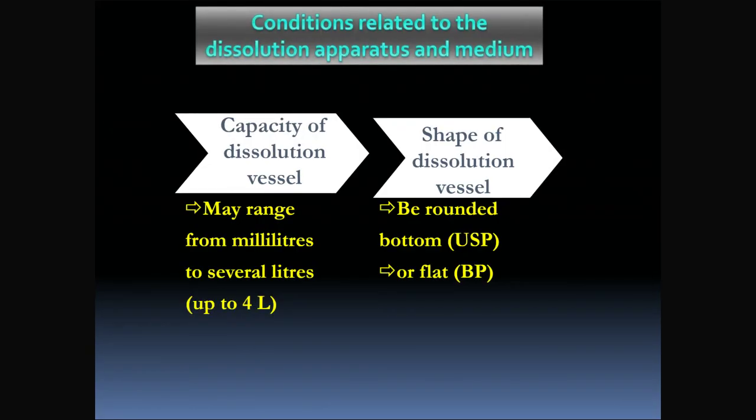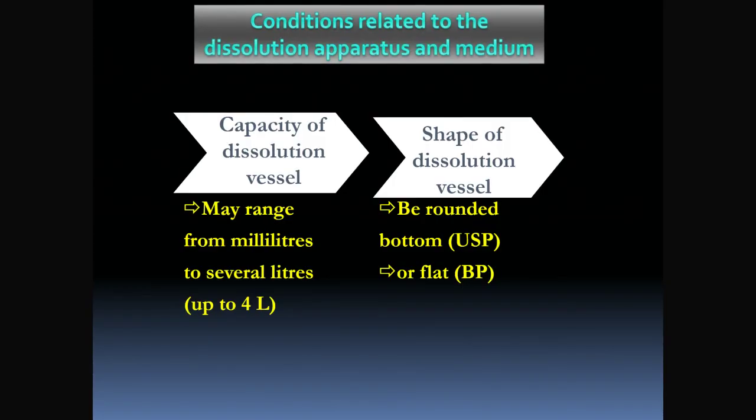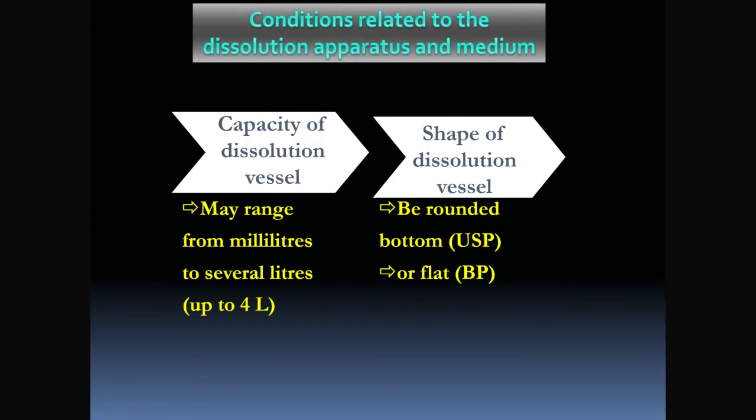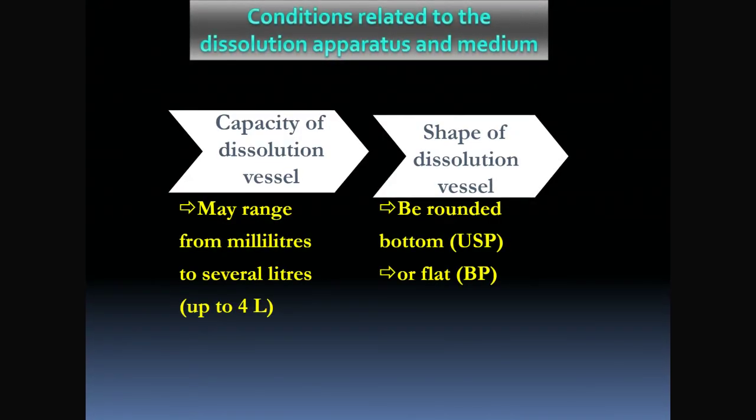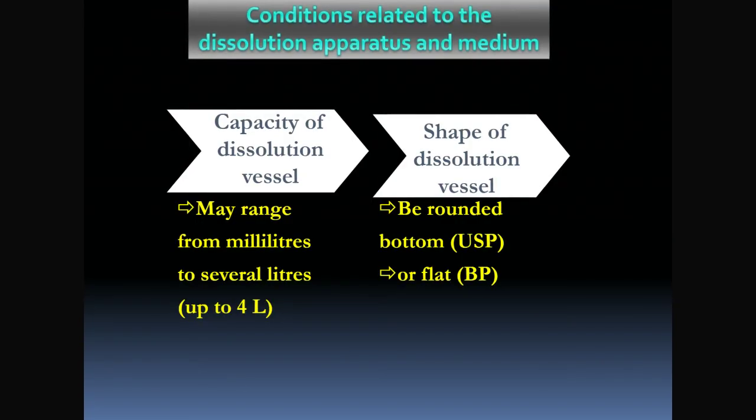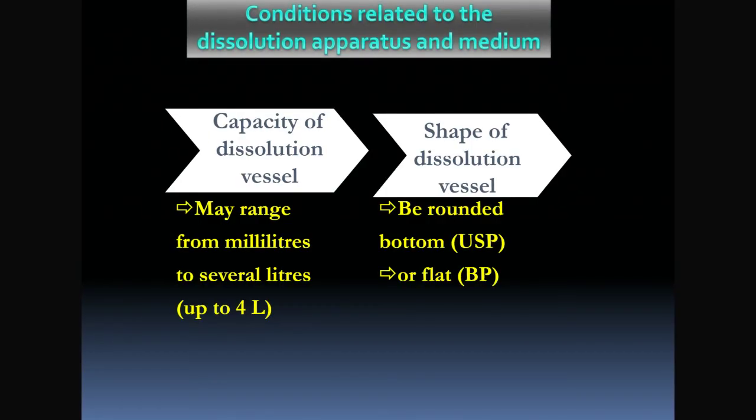Observe the two distinct geometric profiles, the hemispherical rounded bottom standardized by the USP and the flat bottom specified by the BP. These shapes are engineered to control the local Reynolds number at the base, with rounded bottoms specifically designed to eliminate stagnant dead zones where solute accumulation would artificially thicken the diffusion layer. Given these physical constraints, how would transitioning from a rounded to a flat bottom alter the mechanical shear stress experienced